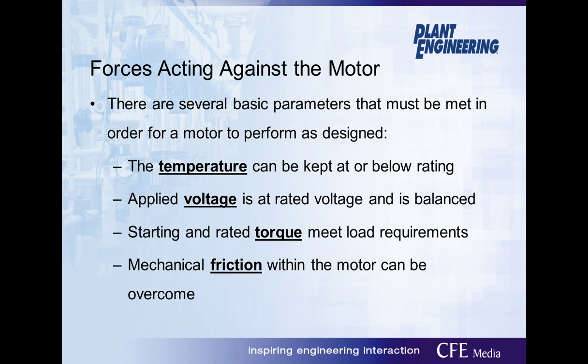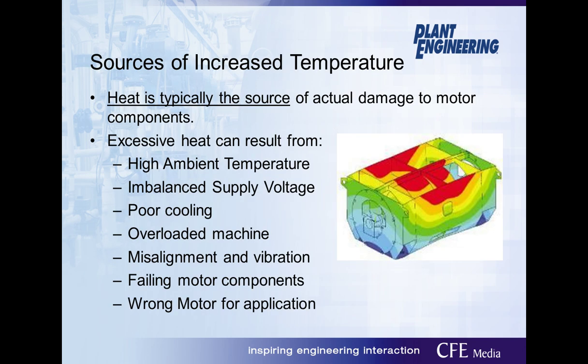Next, we will take a look at various forces acting against the motor during operation. For a motor to perform within design specifications, running temperature must be kept at or below insulation class rating. Applied voltage should be as close to nameplate rating as possible and balanced. Starting torque and rated torque need to meet the load requirements of the application. And mechanical friction within the motor can be overcome during startup. Now we'll expand on those four topics.